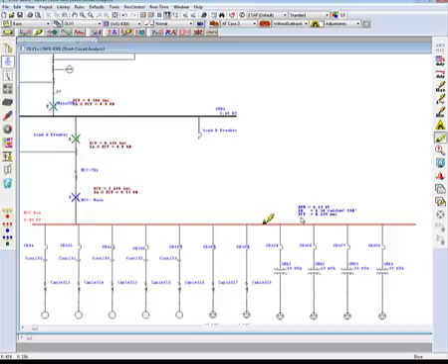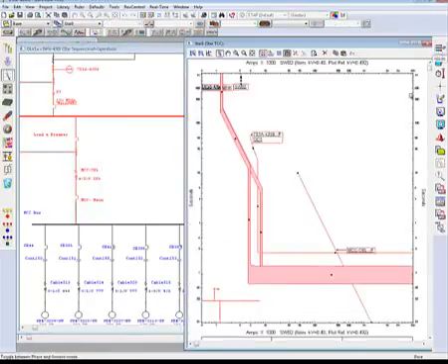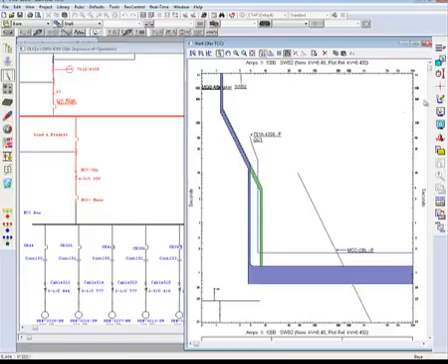And that is reflected with the incident energy and the fault clearing time results shown here on this bus, 0.135 seconds. Now, this current that is passing through the device is approximately 8.5 to 8.8 kA. Let's generate a TCC curve of this portion. Using the crosshair, I'm going to go ahead and mark my 8.5 current, which is somewhere around here.